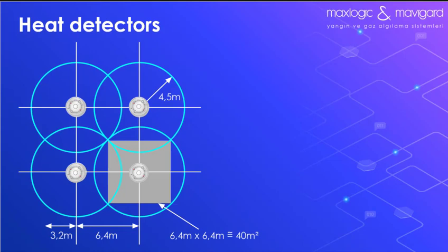If the projected area has a slope ceiling, for detectors at or near the top, the horizontal distance given above may be increased by 1% for each degree of slope up to a maximum of 25%.